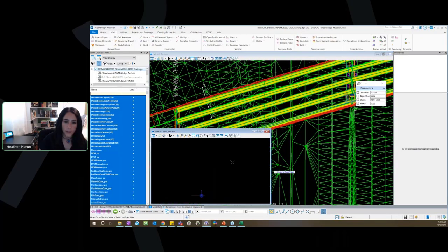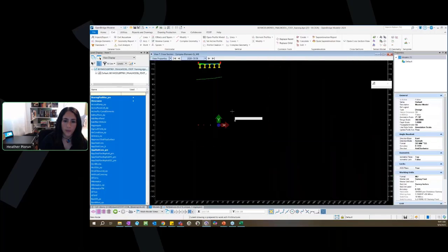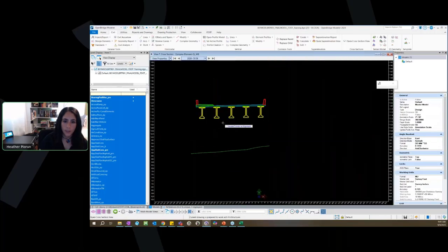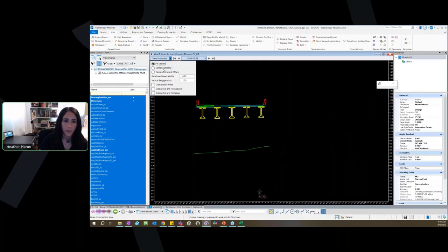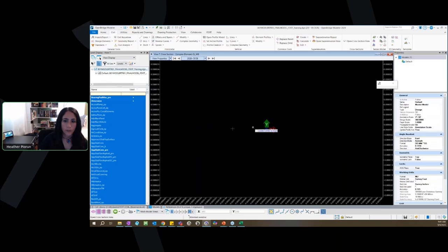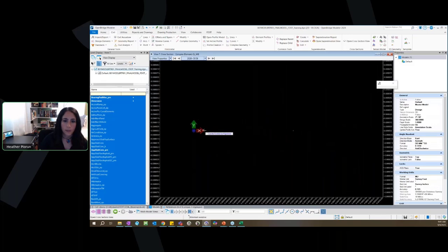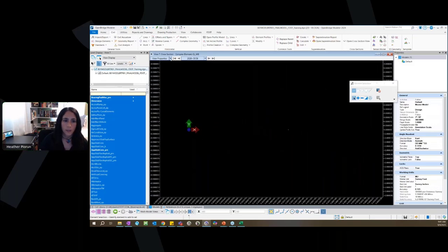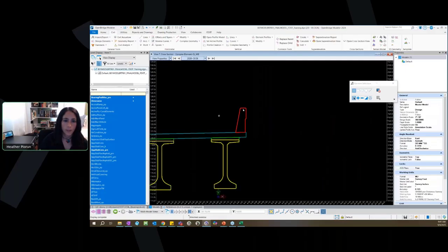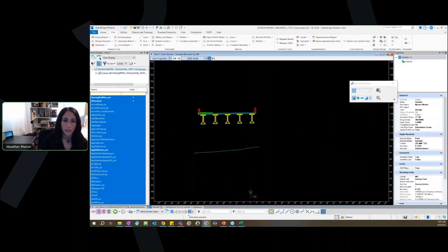And then you can go into another view, select the open view, and now we've got our bridge model section view, and we have the terrain there as well. So you can go through and, oops, use center backbone again, and then you can click through and see how that terrain varies, how the profile varies, how the haunch varies, and you can click through however many feet.